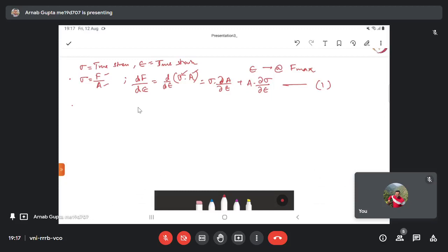This will happen till the necking begins. At the onset of necking, voids start appearing across the cross section, and the voids coalesce with each other, and as a result the cross section decreases drastically. But before the necking region, the volume of the material is constant.